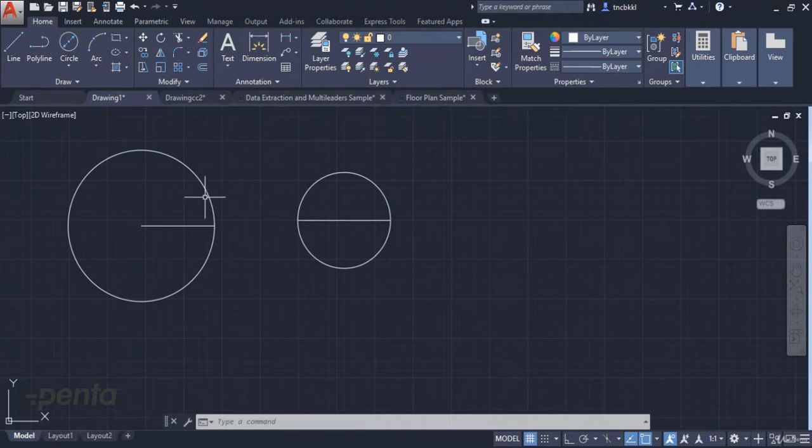Here, what we call the radius is, when drawing a new circle, we first set a center point. We later set the radius length over here, as you can see, and create a circle. If we have the external diameter of the circle we want to draw, we can directly set the external diameter instead of splitting it in two, and we can create a circle.